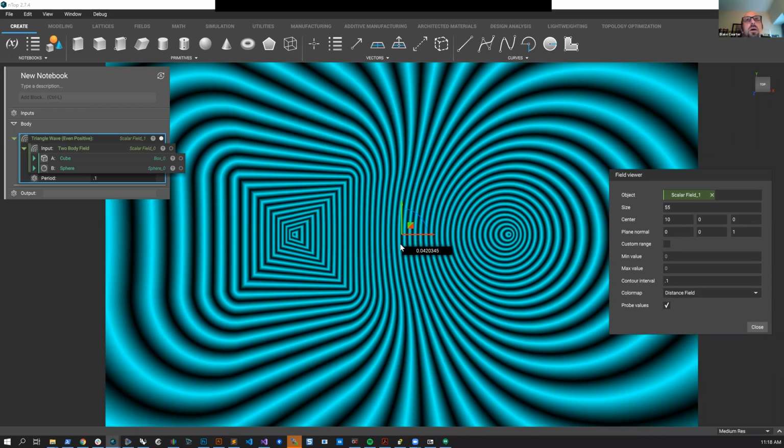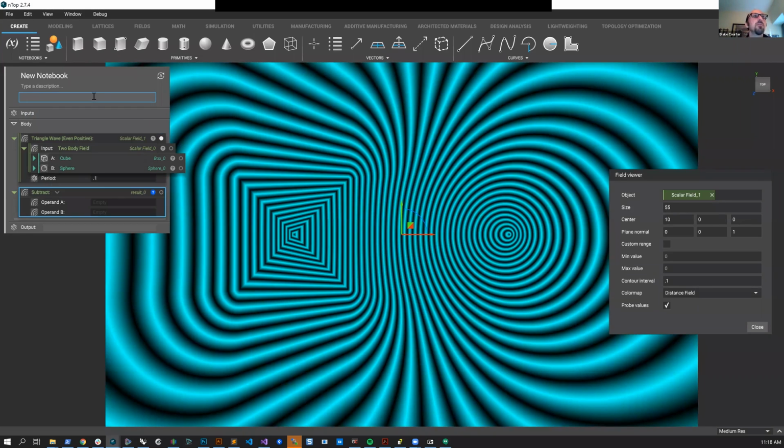And the reason we're doing that is we're going to thicken them. Again, you could use a thicken operation or an offset operation. Because this is a video about intermediate level modeling, I'm going to do things with the lower level values and just offset a little bit. Now, this is actually being offset. This is still our non-dimensional field.